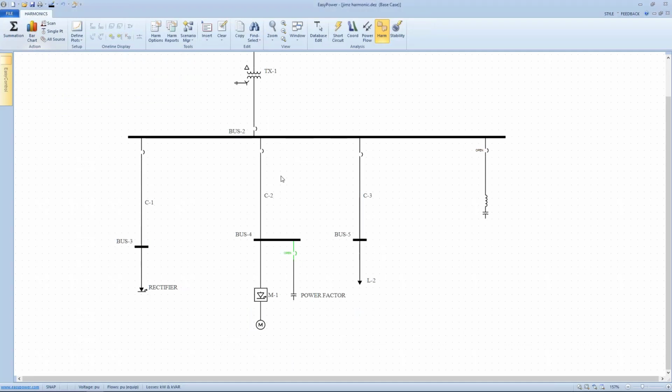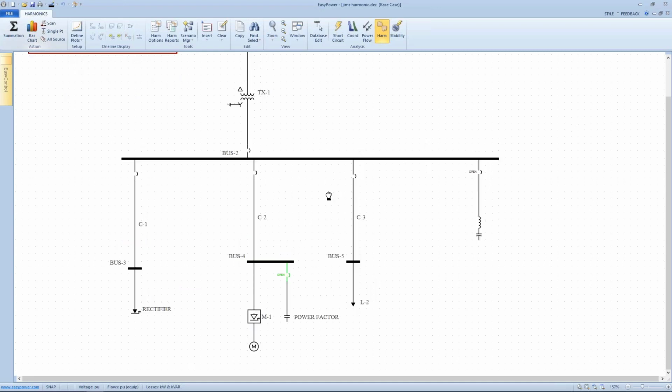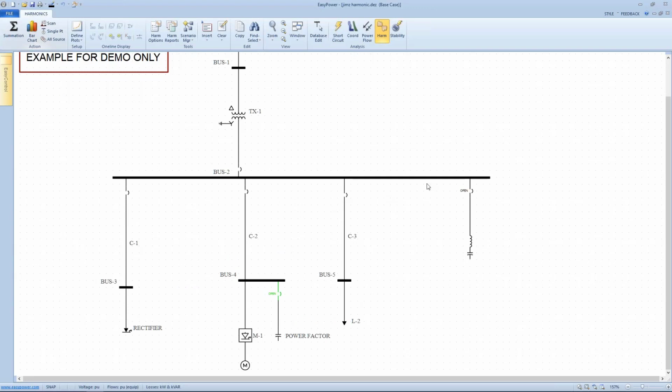Now, just while we're here, I'm going to talk a little bit about mitigation. The first thing, frankly, that you do is not just throw another filter on there. You want to look at other potentials, and if the cause is the controllers and pulsing of different large motors, there are methodologies and steps to take that give you more flexibility rather than just throwing on a filter.